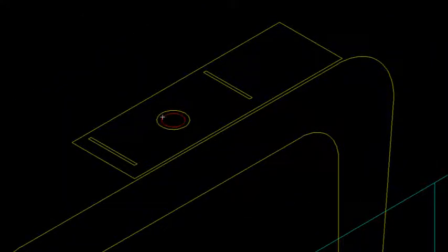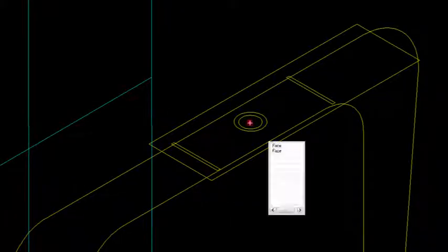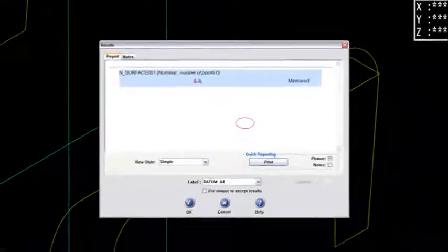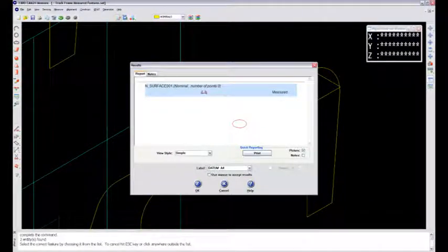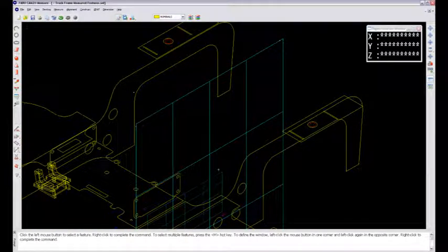And now I'll zoom out and pan over to this corner. Now, there will be a couple faces it finds. There is the patch I'm looking for, and I'm going to call that datum A4. All right, very good. So I've got 4 up-down patches that I'm calling A, and that's actually what the drawing wants me to measure to. They're all 4 called datum A.